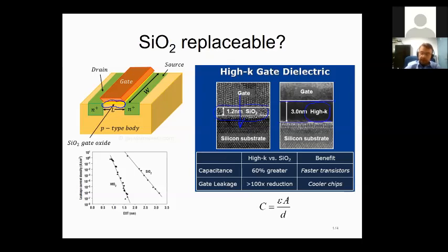These high-K dielectrics will withstand these electric fields and will stop the electron conduction from the gate down to the silicon. If you stop that, you will also prevent the leakage of the current. The current won't be leaked away, so you consume less and less power. Hafnium oxide is one of those types of oxides, unlike silicon dioxide, so it doesn't allow the leakage current to occur.